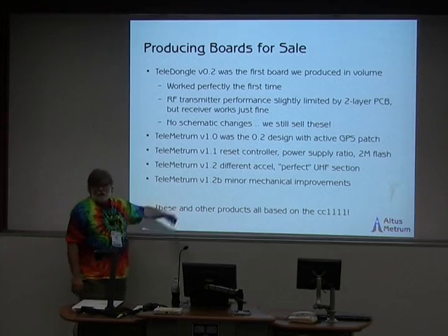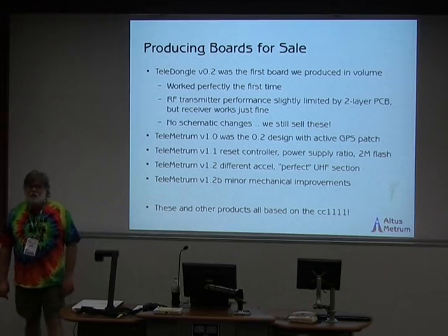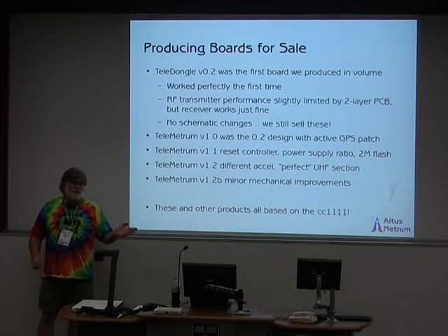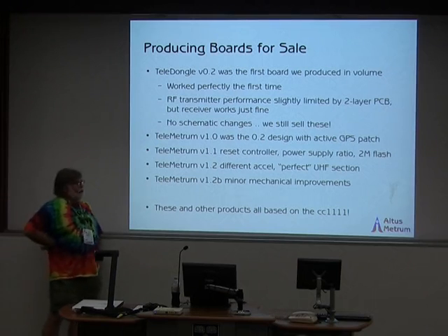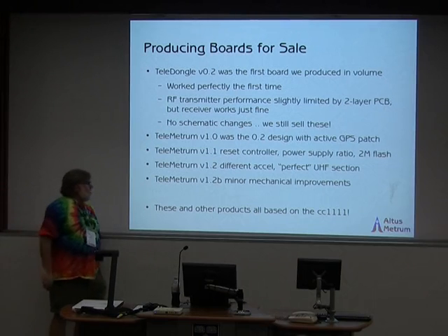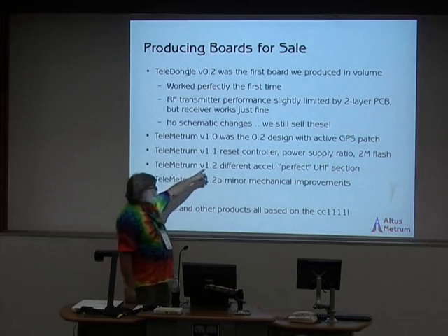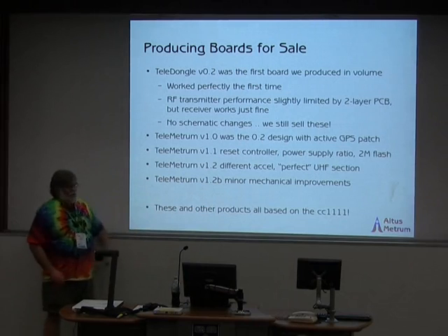On version 1.2, I never saw a board with less than 10.1. They were all somewhere between plus 10 and plus 10.5 dBm output. So that's the one where I finally got the filter design, the layout, and the component selection right to actually achieve what that chip's capable of. And we really like that design. The only changes on 1.2b, which